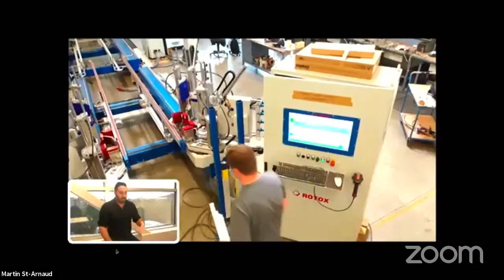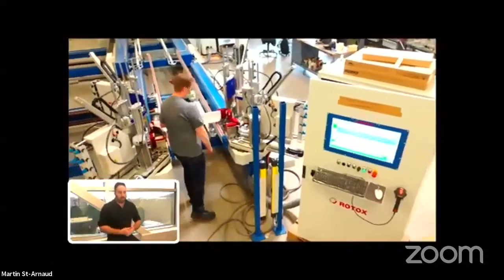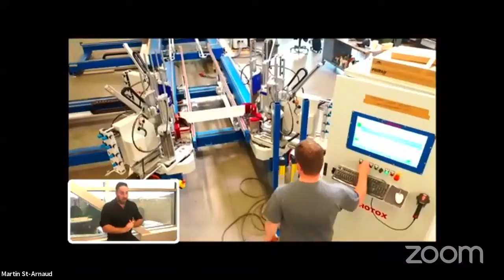Well, high-speed welders do have servo motors in them now, so they are actually measuring all the parts that are coming into your welder. So let's say for any reason you would have a 1008 part, the welder is going to know that the part is too long, and it's going to burn off the extra millimeters on each side to end up with your 1,000 measure at the end. So it's really helping when you're going down your assembly lines, where you're going to be integrating your sash into your frame or the glass into your sash. If you do have those exact measurements every single time, it's going to make your life a lot easier.